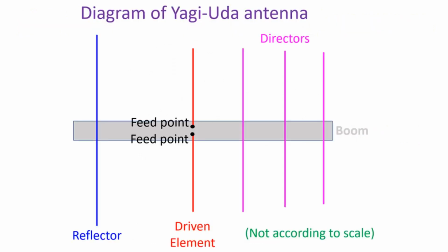An antenna with lower bandwidth will not cover the entire allotted frequencies of a given amateur radio band. For example, some antennas are meant for the CW end of the band, while others are meant for the upper SSB part of the band. Bandwidth can be expressed as the range of frequencies at which the SWR is less than 2:1. Using thicker antenna elements is often mentioned as an option to increase the bandwidth.